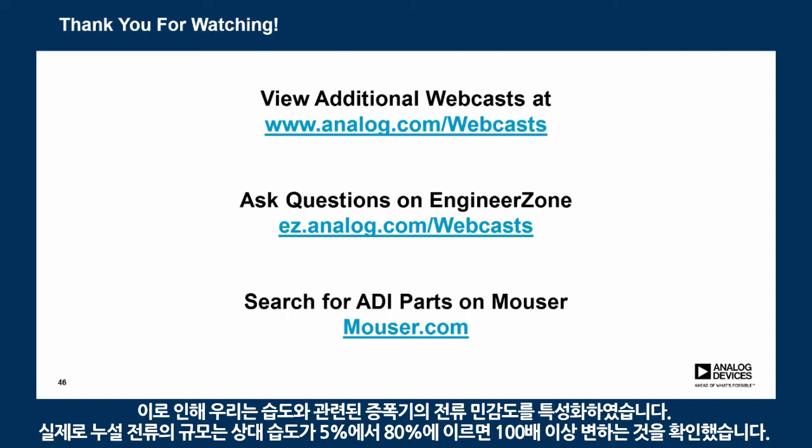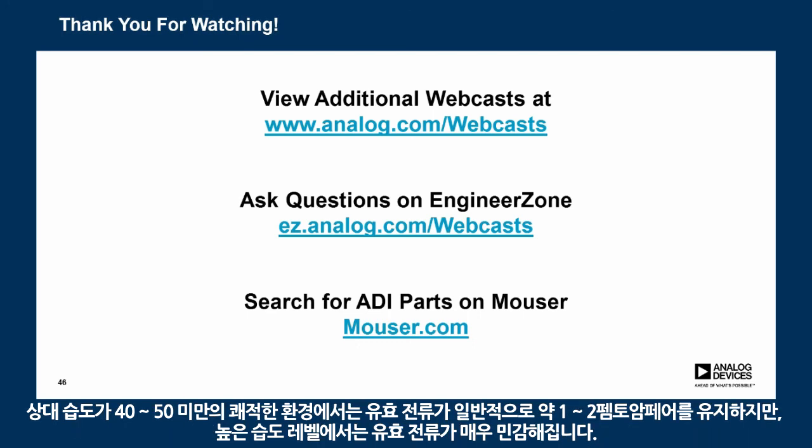While characterizing the amplifier's current sensitivity to relative humidity, what we learned is that the magnitude of leakage current changes by a factor of 100 or more when we sweep relative humidity from 5% to 80%. The effective current is still about 1 to 2 femtoamp typical for a controlled environment of less than 40 to 50% relative humidity.